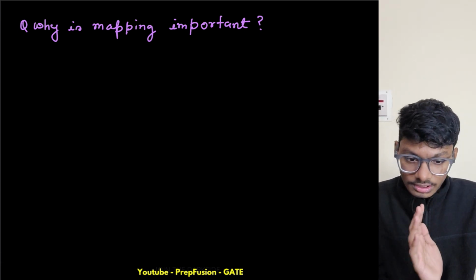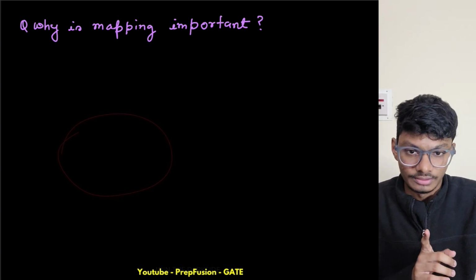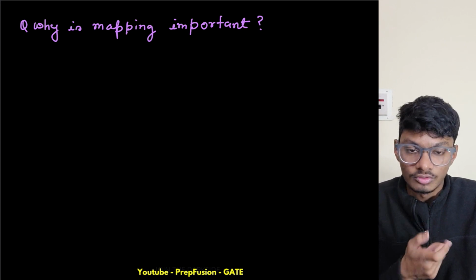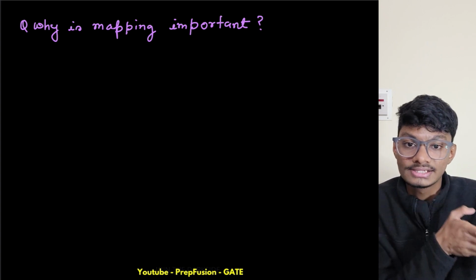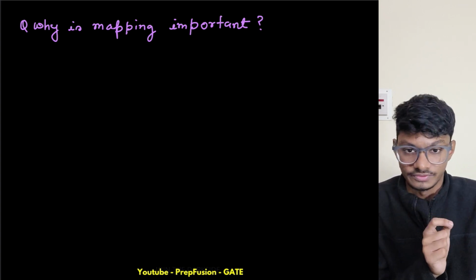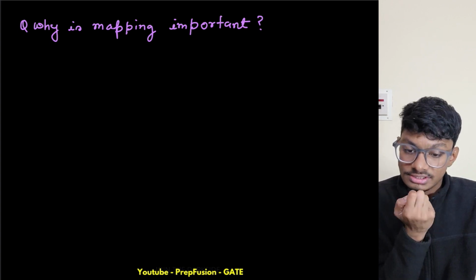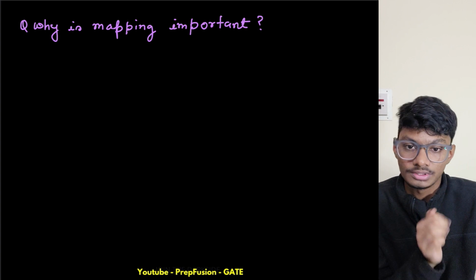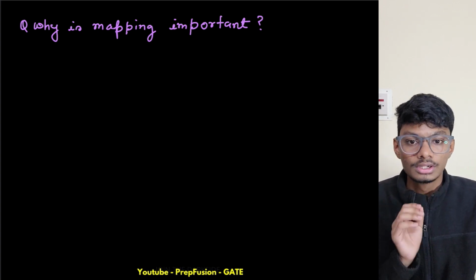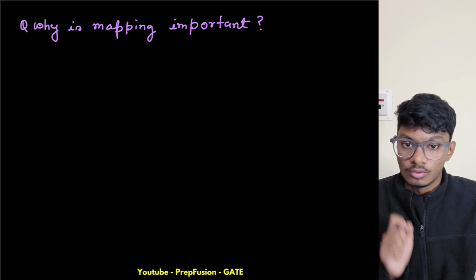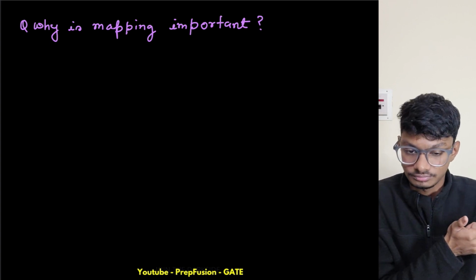What defines stability for a system? For my system to be stable, I have to check that even if there is one pole lying on the right hand side of the S plane of my closed loop transfer function, CLTF, then for sure 100% my system will be unstable. That is correct. That is what we did in the Routh Hurwitz criterion. We found out how many poles are on the right hand side of the S plane.